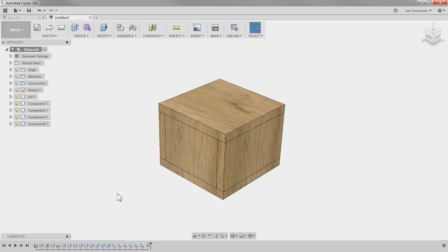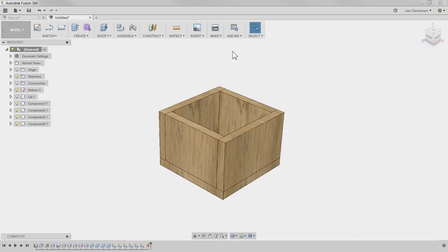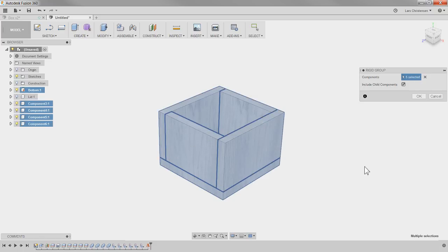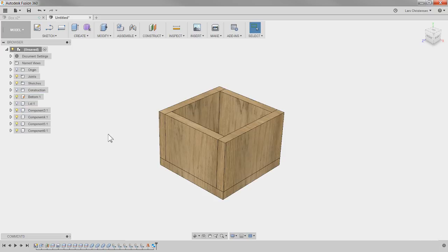Then to make the other ones fixed to that one, I'm just going to hide the lid, because that one actually has to move. All the other ones I want to nail in place, glue or screw, whatever you want to do. I am going to go up and use the rigid group, which means I'm telling everything that these things are all part of one group, included together. And since we grounded that one, you see how there's a little thumbtack on the bottom up here? Everything is glued together and not moving at all. Yay. Okay.